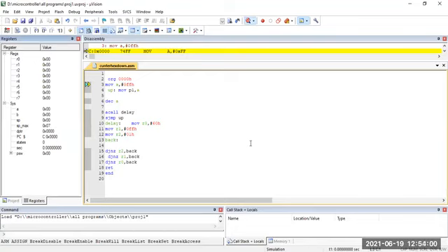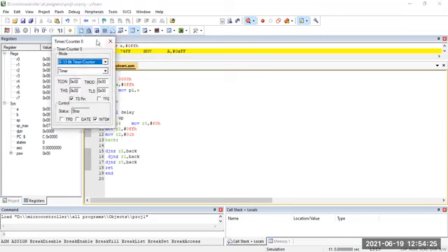Can you try running the timer programs? You have to type and run the timer programs. The thing is, you have to observe the result: go to peripherals, in the timer. If you're writing the program for timer 0, you have to click timer 0. Timer 1 means timer 1. You have studied only timer 0 and timer 1, not timer 2, right? Take timer 0, and then observe here. If it is mode 1, take this one and observe the values.